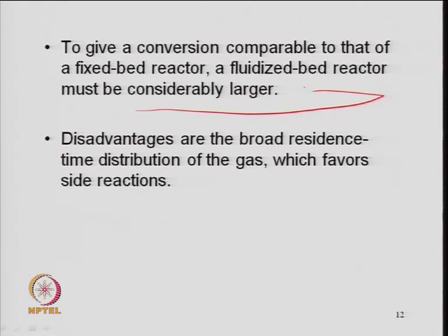So, the disadvantage, that is what I talked about already, is a broader residence time distribution of the gas, which favors the side reaction. So, that is why fluidized bed reactors may not be good for those operations where the fixed bed reactor works, right. If the fixed bed reactor works properly, then one should not consider a fluidized bed reactor, right. So, fluidized bed reactors are preferred only when the catalyst is to be replaced again and again, right, or you need a fine powder which is to be reacted, solid reaction, reacted continuously in the bed, and at that time you have to make it a continuous type of reactor.